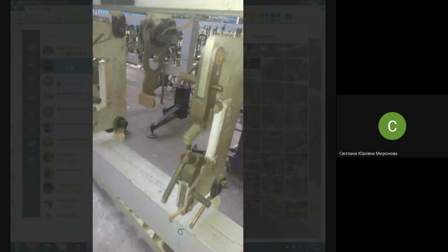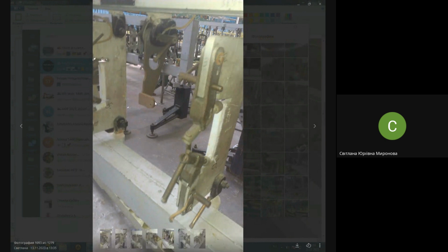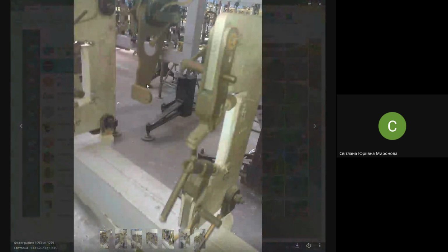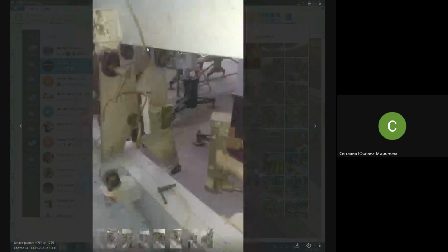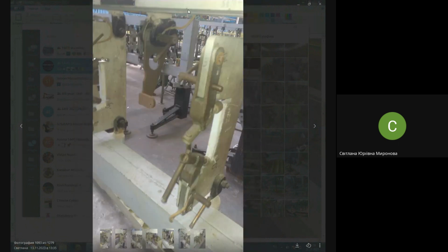It's developed, designed. By the way, here is one more locator, a locator of CFH, but pay attention to this bracket, this thing in the middle with a hole. Now it's not joined to one or another locator of the contour, it's joined immediately to the skeleton, to the structure of the carcass object. Depending on how far locators are from each other, you may join it either to another locator or immediately to the skeleton of the jig.